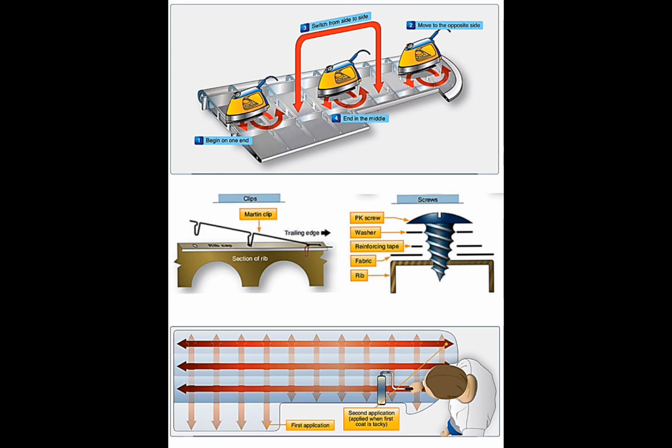How are wrinkles removed from cotton fabric? Wetting the wrinkles and allowing it to dry. When is finishing tape applied? After the second coat of dope is dry. How wide should service tape be when used to cover the trailing edge of an aircraft wing? 3 inches.